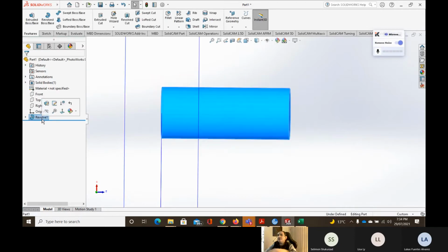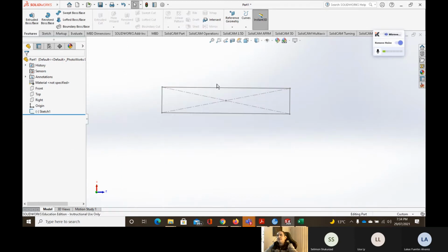We'll go back to the actual part we sketched at the beginning. Just remember that this will be my datum point here. The z equal to 0 and the x is equal to 0. As I'm going to go up to that point, you can see that the x is 20. But when I'm going to write down the coding, I'll write down the x here is equal to 40, because the diameter at this height is going to be equal to 40.